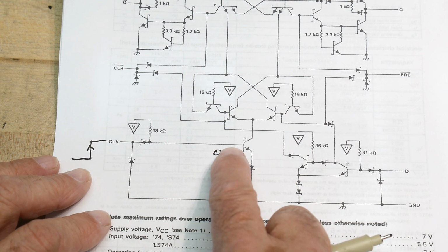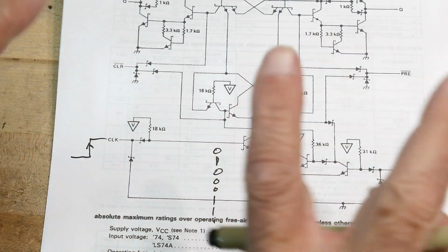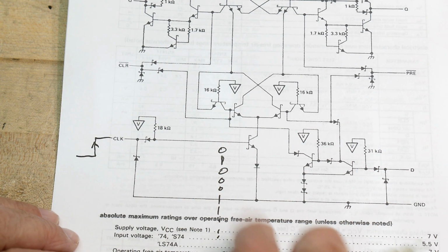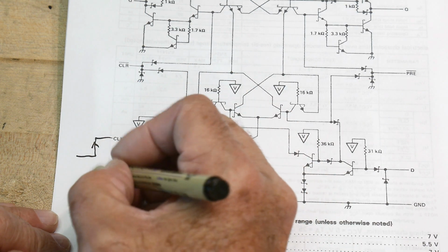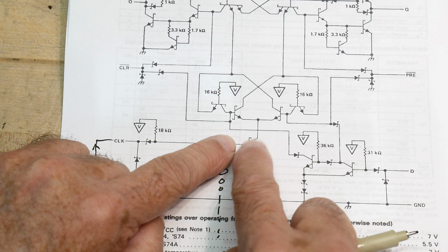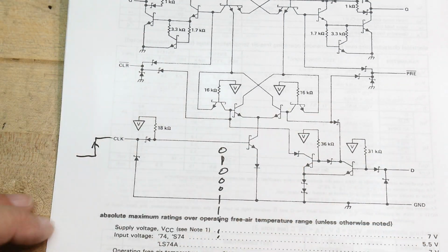That just means that it went high. Not that it's actually looking at an edge. It's just looking at a high state. And so, yeah, it's very, very interesting. And it'll trigger somewhere along that edge, depending on the base emitter junction here, and this diode and stuff. There'll be some level at which it will switch, but then it just won't switch anymore.